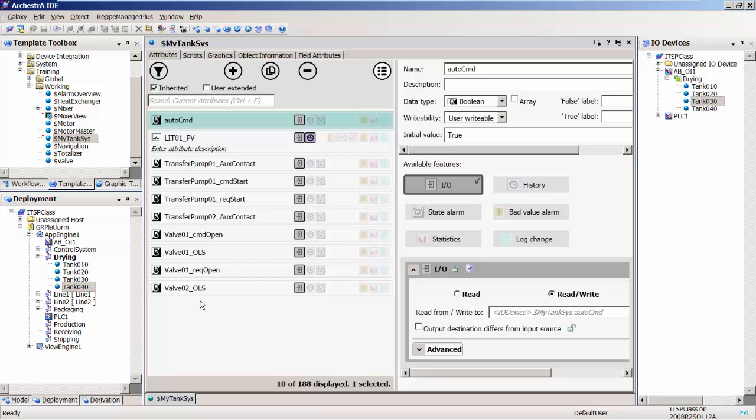One thing I hear from some customers is, hey, with Rockwell we can browse down into the PLC and pick tags. I think this is easier than picking tags. We don't need to pick tags. We just make a new instance. We automatically link to those variables in the ControlLogix processors without having to browse for every variable and pick and choose. It does it for us automatically. So I think the ease of use is great here, where I can just drag and drop things and point to my PLC, and I automatically bind that IO to the PLC.